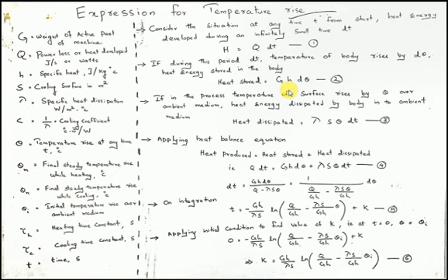As the machine is running, during this short time duration dt, definitely the temperature of the surface of the machine rises by theta over the ambient medium. I have already mentioned, the ambient medium is actually the cooling medium. In machines which you have seen in your labs, the cooling medium is actually the air surrounding the machine. So while the machine is running, the temperature on the surface of the machine goes above the temperature of the ambient medium, that is, above the temperature of the air in the case of the machines which you have seen in your labs. Since the surface temperature is greater than the ambient temperature, definitely some amount of heat will be transferred from the machine surface to the ambient medium.